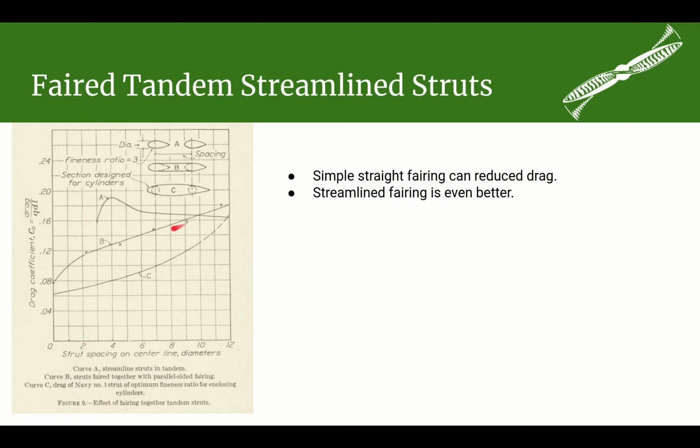So at least for this ratio of about 3 up to 10, you actually have less drag than doing nothing. So that's kind of nice. But after you get up to that ratio of about 10, the drag starts increasing. On these struts, diameter is basically the thickness of the strut. So if your diameter is 1/10 of the distance between them, let's say you had a 1.2 inch diameter, then up to a distance of about 1 foot, you could put a sheet on the top and bottom and reduce the drag on these struts. Well, that's not much of a separation.